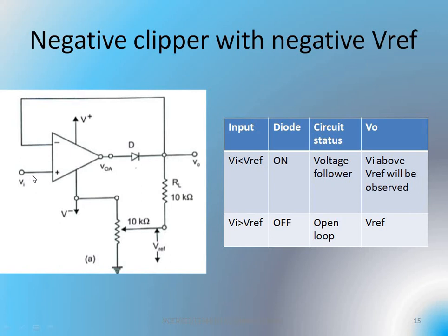Here you can find that the positive signal is provided. This positive signal will be applied here. So the diode's anode is receiving a positive signal, and here you can find that a negative reference is provided. So here you assume that here it is 5 and here it is 10. So when you have 10 as its input voltage, what you have? You are having sufficient negative voltage at the cathode, and here also you are having a sufficient positive voltage with respect to the anode. It means that the diode will be under on condition.